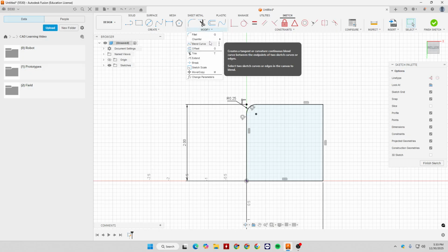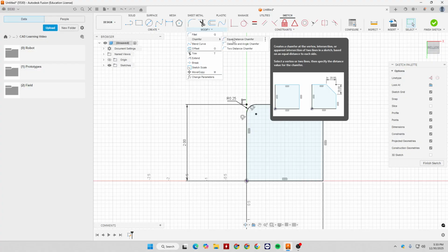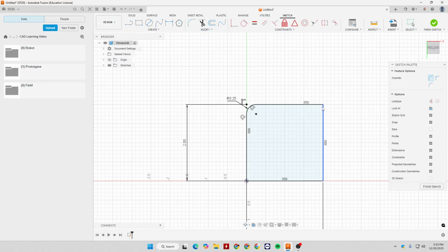Next up, we have the chamfer. There's different types of chamfers, but essentially this will be another way to smooth an edge, but it'll be a straight line, just cutting off that corner. So an equal distance chamfer, if we select this corner, it will be the distance of this edge length. So if we do a 1 inch chamfer, it will be half the distance of this length